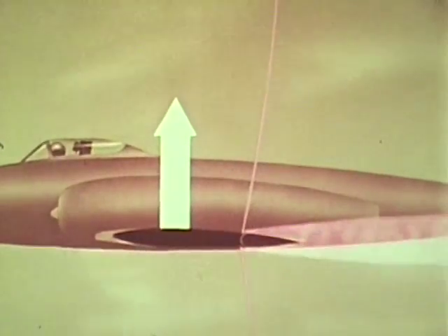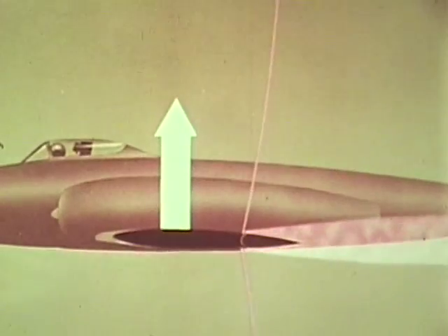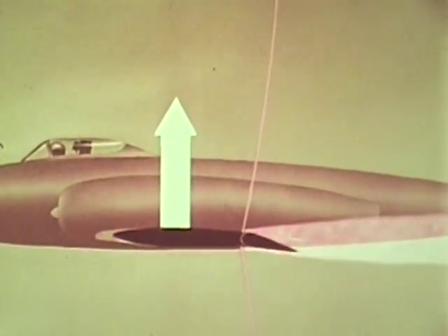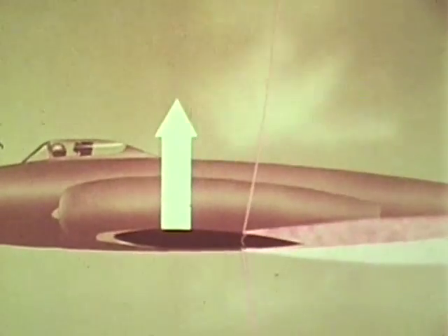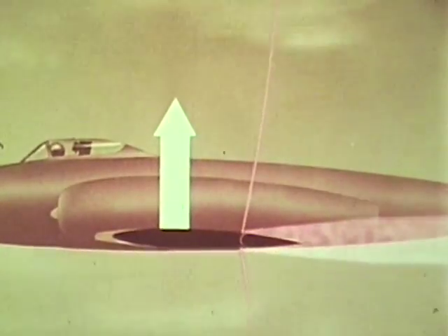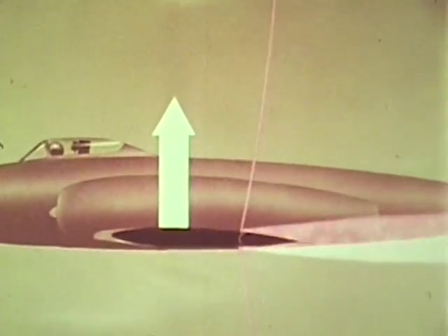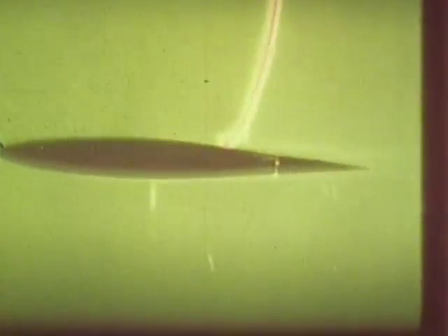Secondly, the control surface is not fully effective even behind the shock wave, for it's moving about inside a region of separated airflow, which, although turbulent, is aerodynamically dead and can't exert much force on the aircraft. But this turbulent wake can cause violent oscillations of the control surface itself. They are accompanied by large fore and aft movements of the wing shock waves. In this picture, the movements have been slowed down 40 times.